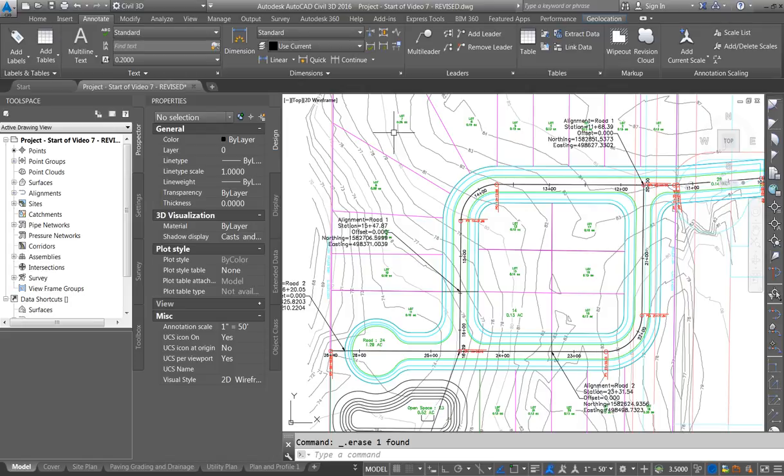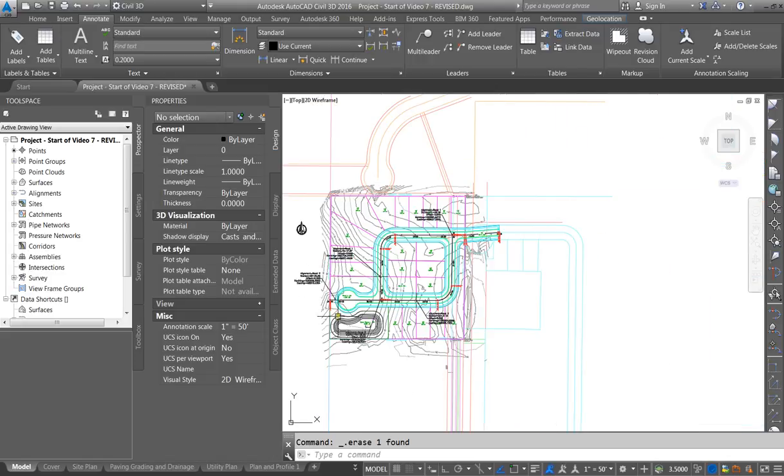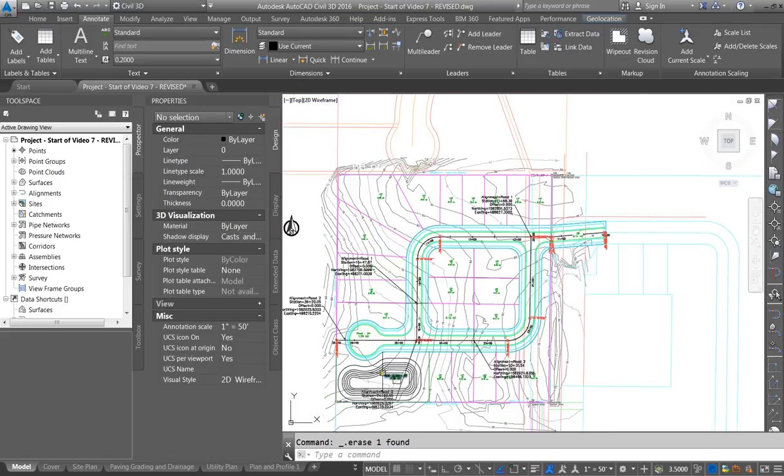Because here's the thing, the reason I have to label the parcels now is I have to know the distance. So when I'm grading the center line of the road, I can think consciously about the elevations that I have to tie into along this west line, south line, and north and east line. So I want to go ahead and do the labels.